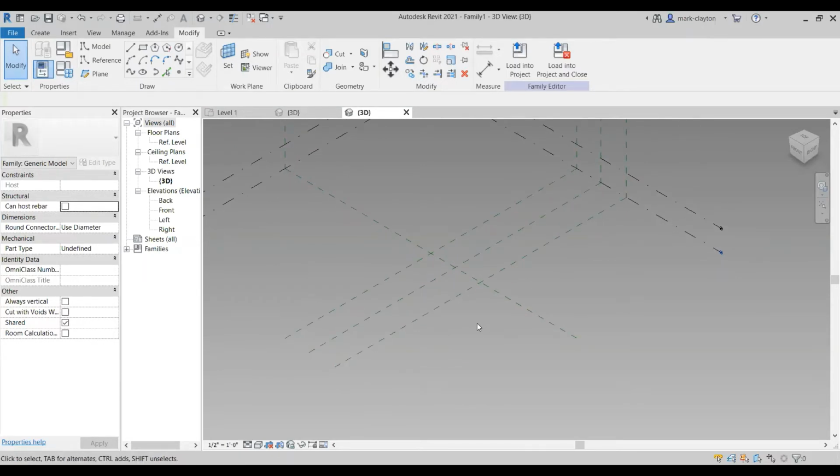Now, to turn it into this thing called an adaptive component. The notion of an adaptive component is that it adapts its shape and form when you use it. So you can draw it, but when you draw it, you're specifying the relationships among the parts, but you're not specifying the dimension. For convenience, we're drawing it, it has a dimension, but we're really specifying the relationship of parts.